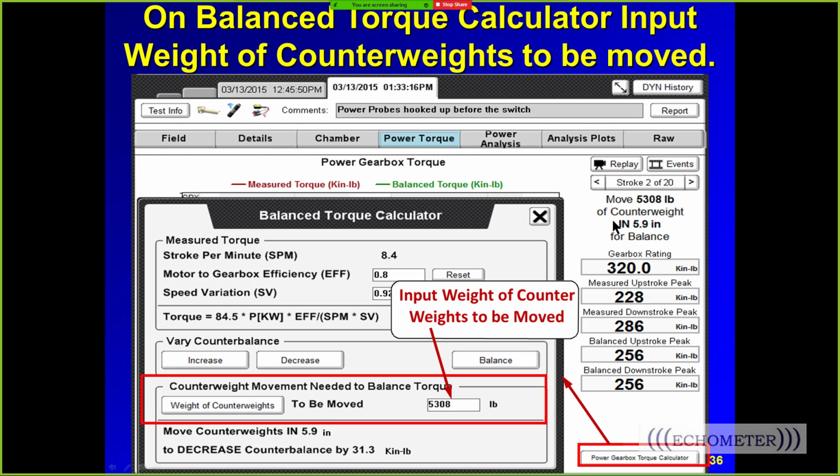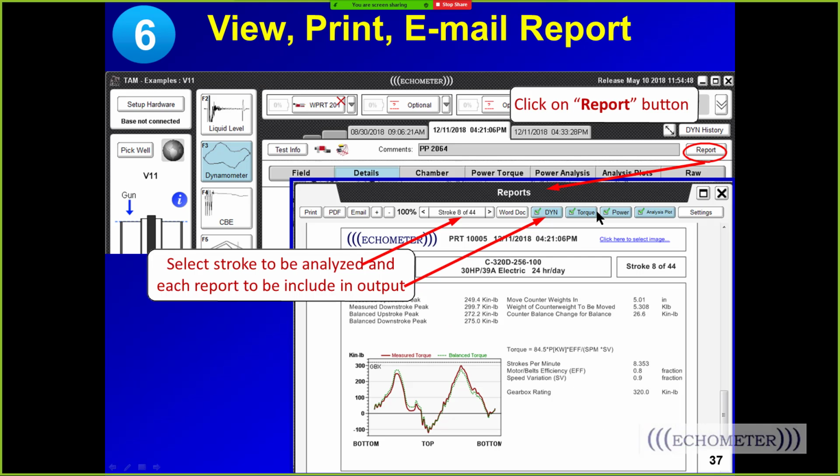My preference is to have all the weights lined up. People sometimes ask that. I don't like to have the unequal counterbalance moment on each side of the gearbox shaft. I think that can cause damage to the gearbox. I've been told that, and then I've been told more recently it doesn't matter, but I tend to still not want to make uneven counterbalance moment on each side of the gearbox shaft. So I tend to keep them equal spacing, top and bottom of the weights on the crank.